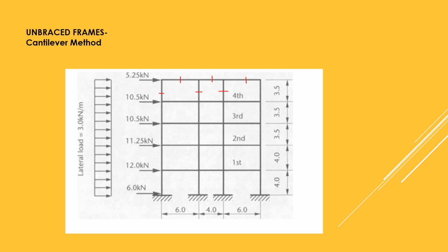In this case, first we have to do the gravity load or vertical load analysis as described in the earlier case of statically determinate structures, and then do the lateral load analysis part also. Then we have to combine both together to get the complete structural analysis. This solves the total structural analysis manually, but it is valid only for simple regular low-rise structures.